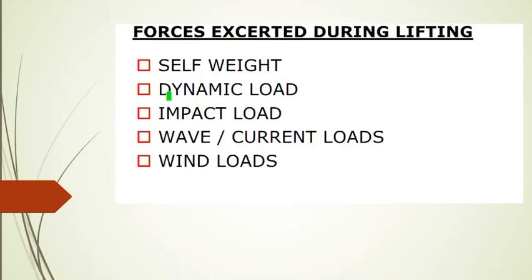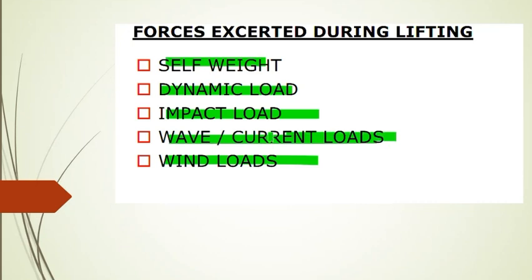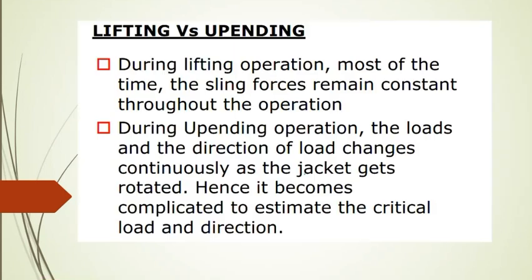And forces etc. during lifting: self-weight, dynamic load, impact load, wave and current loads, and wind loads. When we are lowering the jacket structure into the water, wave and current loads will also be experienced by the jacket structure.